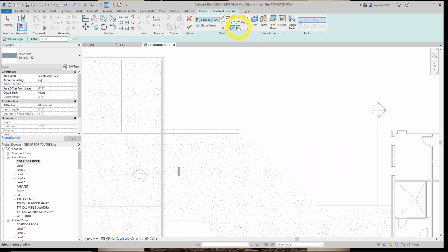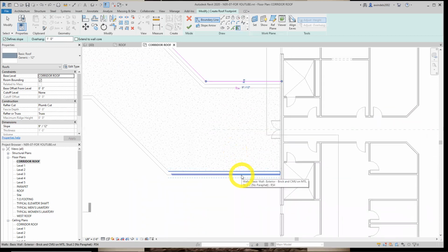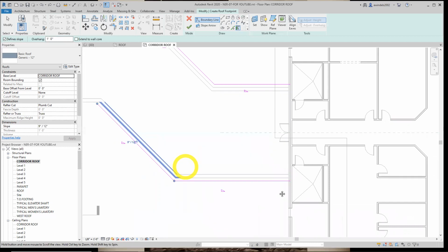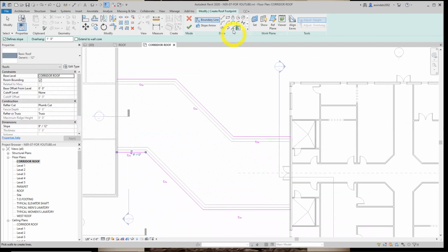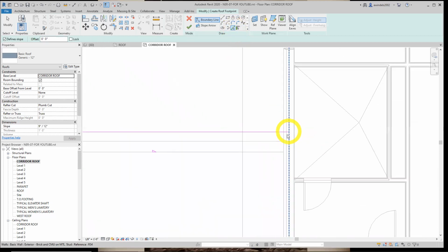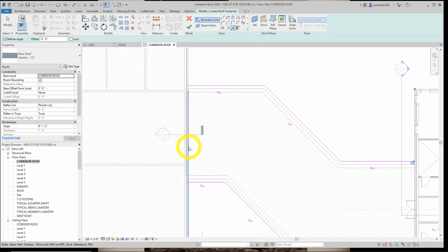On your first command, you could easily have the pick walls going too. The gable ends, we're definitely going to use pick lines, but does about the same thing. It's just a little easier to not go to the wrong side. Make sure your overhang is on the outside, right? That's where your roof's going to flow out to. That's what they're recommending for the first step. The second step, they're saying use the pick lines command, and let's check which line they get. This one. It's the entire line of that exterior wall, right? Same with this one.